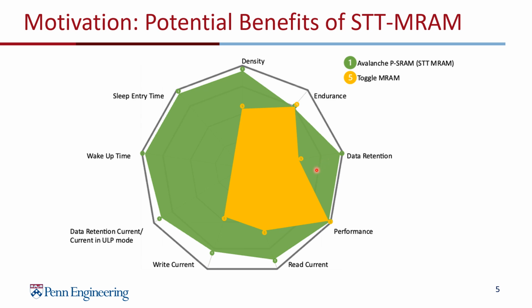Here, a comparison of STT-MRAM and Toggle MRAM done by Avalanche Technologies can be seen. In performance and endurance, the two technologies are similar, but in data retention, read current, write current, and density, STT-MRAM is far better.